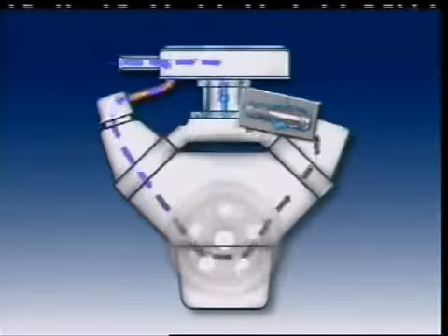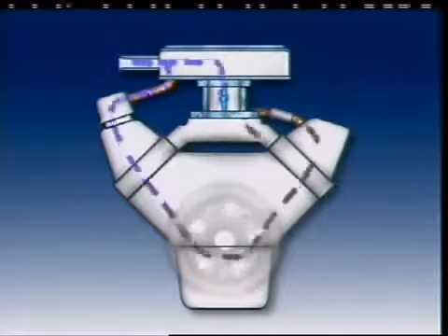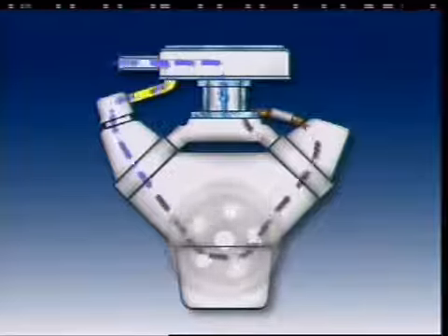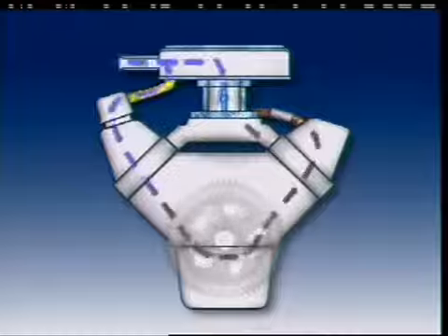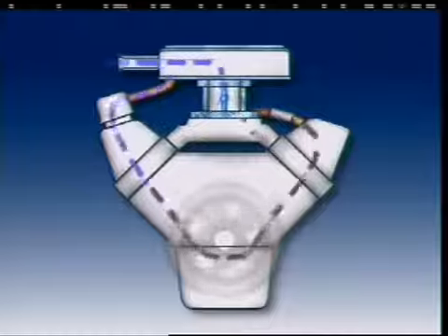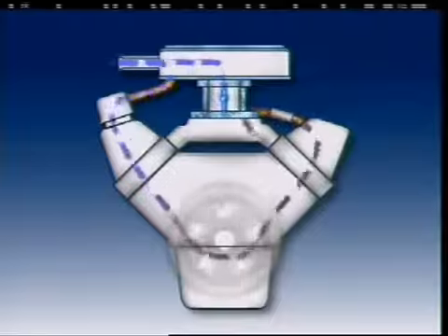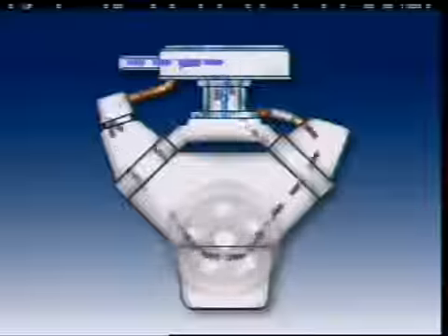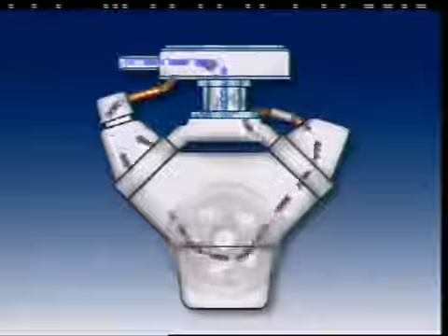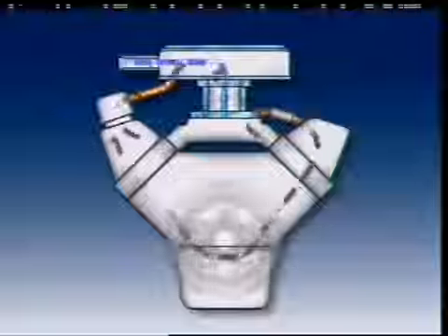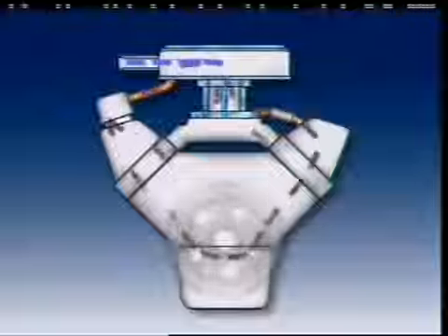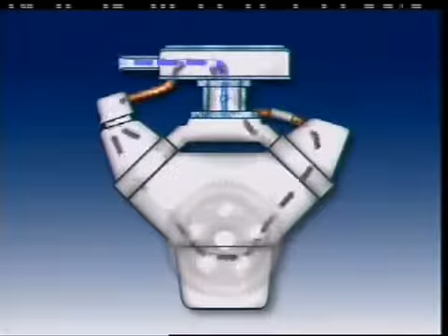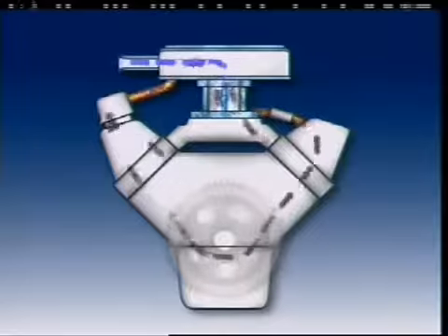The system is designed to remove more air than just blow-by, so there's a fresh air intake, usually at the air cleaner, to direct filtered air to the crankcase. This intake is usually as far as possible from the PCV valve. Wide throttle openings produce maximum blow-by. Gases that can't be handled through the vacuum system are directed back through the inlet connection to the air cleaner, where they join the carburetor intake air and are drawn into the cylinders for burning.